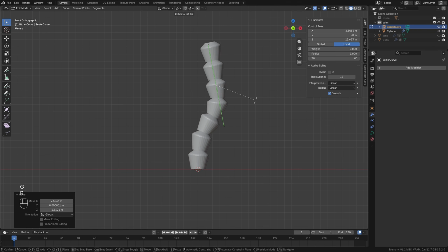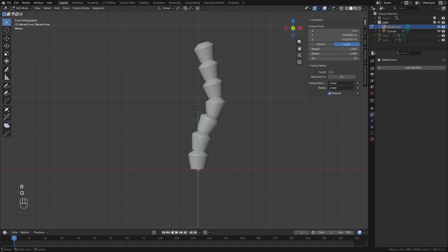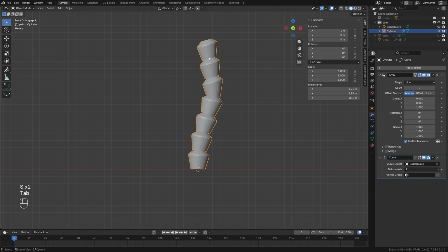Again, we select it, edit it somehow, change it, and our object curves. And we also need to additionally fine-tune the offsets. The scale parameter along all 3 axes for the array modifier we make a little smaller, roughly at a value of 0.93 or around that. And now, along the Z-axis we also reduce, so that they are stacked on top of each other for us.